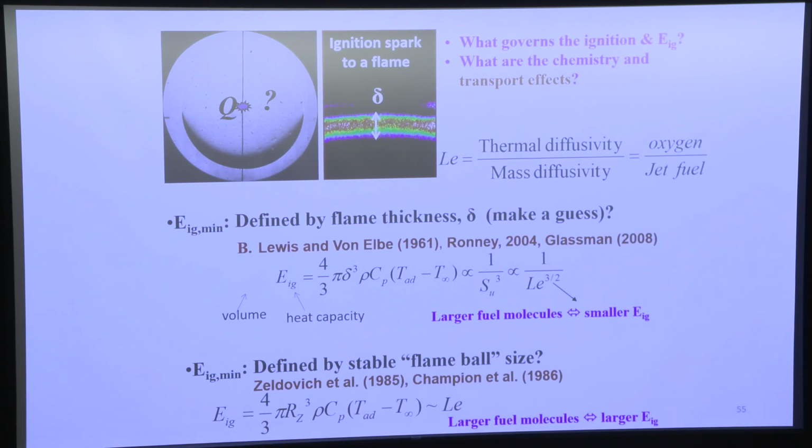No one really observed it before. The theories say it might exist. Theoretically, for an adiabatic flame, Zeldovich says that this is the flame ball. The flame ball either collapses inward or expands outward. And your ignition energy has to be enough to generate a spark the size of the flame ball, because the flame ball is spherical.